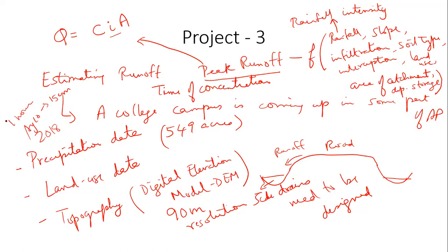It's a very, very extreme thing. This is the worst case possible, that you receive 15 centimeters of rainfall in 1 hour. That's a massive rainfall event, almost unlikely to happen. But just for the sake of calculating it, you just try to calculate it and see what flow rate you get, using that rainfall intensity. Then we can appropriately adjust it, right? So this is the kind of approach that I'm expecting for this project, right?